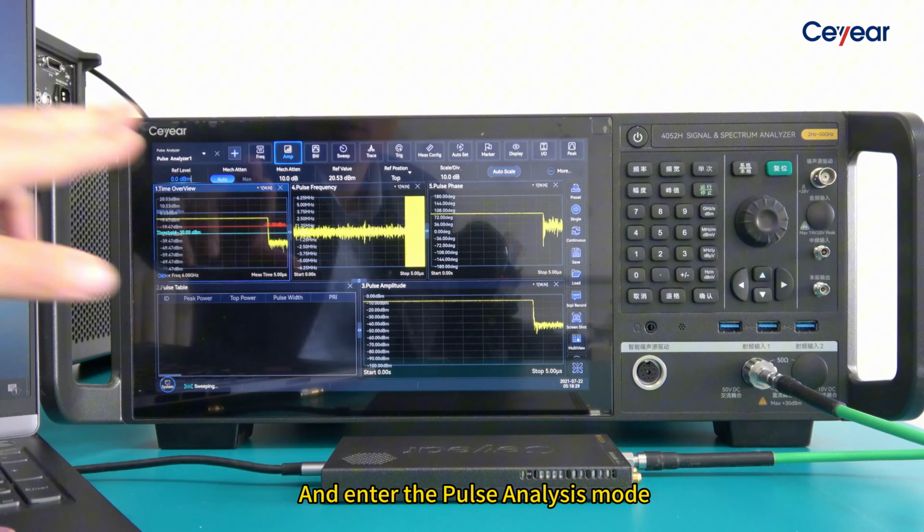It has a very compact size, similar to a Huawei smartphone, and weighs less than 300 grams. So we connect it to a laptop USB port for power supply and communication, and use this software to control it. Then we connect the RF output to this signal analyzer. The current frequency is 1 GHz and the power is 0 dBm. Turn on the RF output and we get the peak at 1 GHz, minus 0.7 dBm.